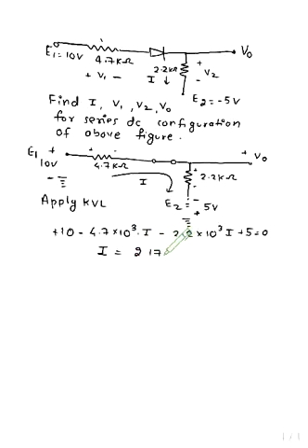I is 2.17 milliampere. So this is the value of I. Similarly we can find V1 is equal to I into R1, and the R1 value is 4.7 kilo ohm, this is R1, this is R2.